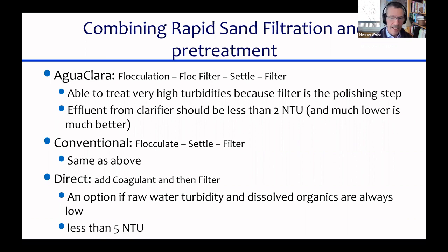I also highlight here, it works if the raw water turbidity is low, like less than 5 NTU, and also the dissolved organics have to be low. If the dissolved organics are high, then you need to have a clarifier built in.